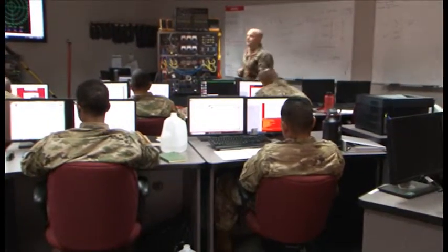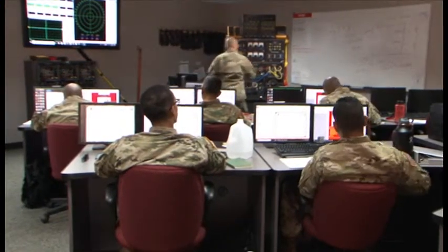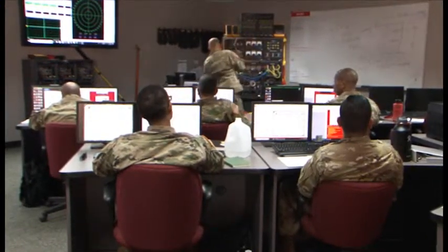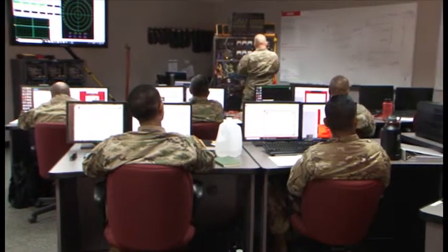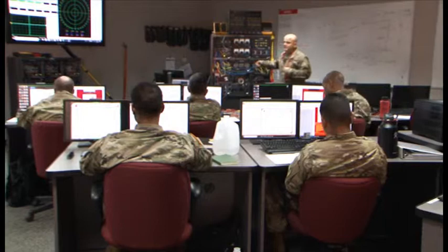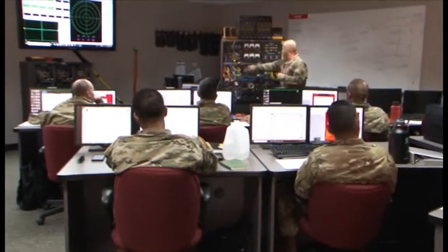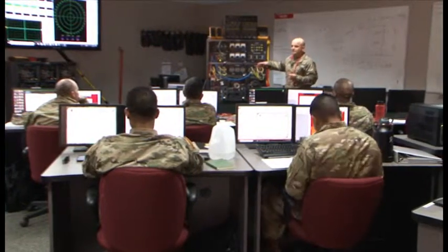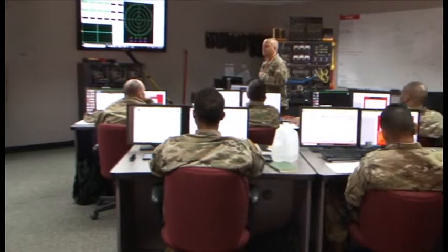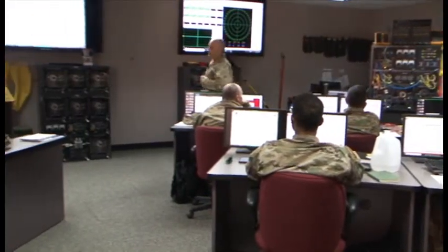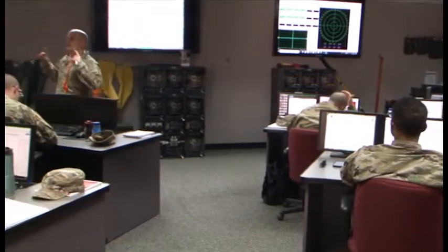Okay, so when we're doing a parallel circuit, over here I had these two in series. Now another way of representing this is to take one of these banks and then jump it over to this bank that's already in parallel, and that's what I mean, the difference in that RL circuit being series versus parallel is just how you're wiring it up. All right? And so in a parallel circuit, the formula is no longer the triangular formula.